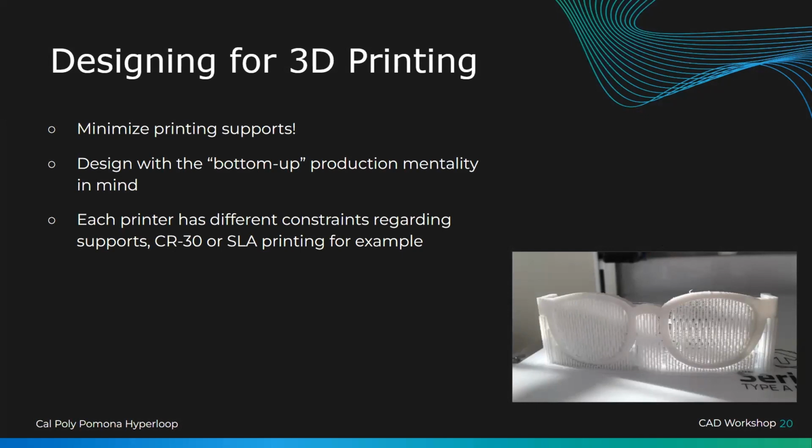Yeah, so this is just an inefficient way of manufacturing. You're wasting material, you're wasting time. It's going to be a lot more labor intensive for you when it's done to get those supports off. We'll go over this during 3D printing, but if you're making something like this, make sure that you're orienting it correctly so that you don't have to deal with all those supports.